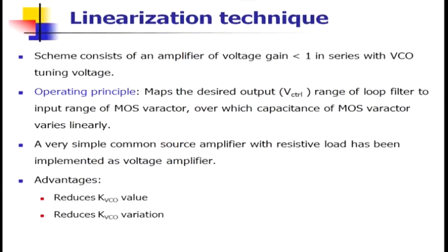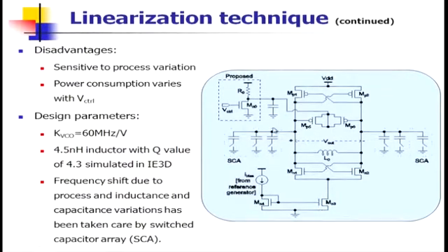So that is the VCO, but on top of that, if you have been asked to change the tuning range further, then I am giving you a modified circuit approach which is pretty simple to do that. So you know this part you have already been taught. This is a complementary cross coupled LC VCO with a bank of switch capacitors, and this is a tail current